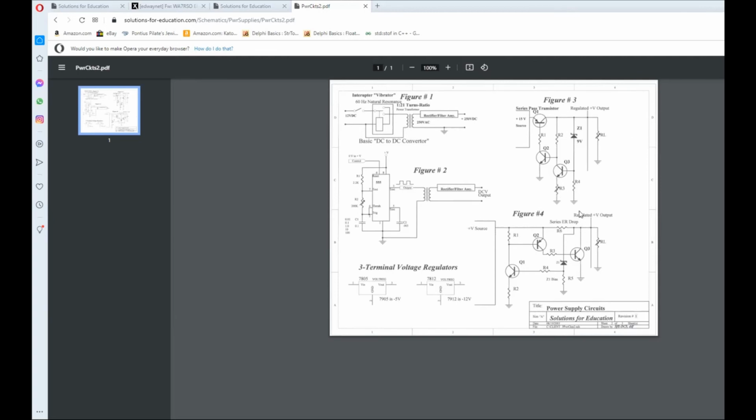All right, enough of that. Let's go down here to this guy. This guy here is obviously another picture of shunt regulation. In this case, this Zener diode here comes over and controls this transistor, which controls this one, which controls this one. And here again, if you pull the load, that means this guy here has got to take up the slack. So the way that these work properly is to take up the variance over here, but not the full load. This is not a good thing to have for heavy loads, because you don't want heavy load pulled in this guy here to take all of that.